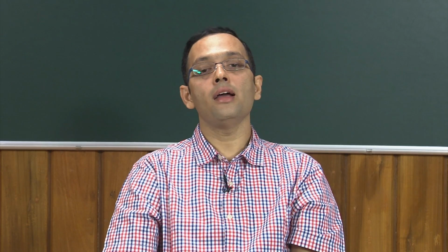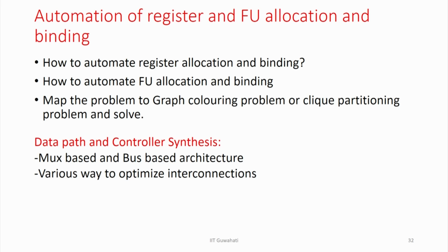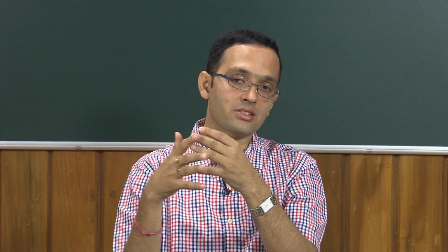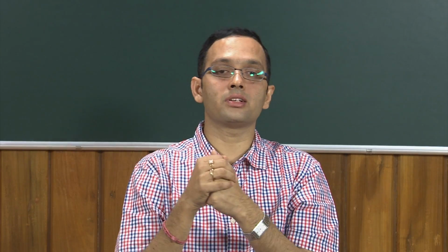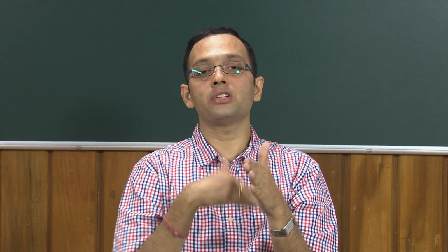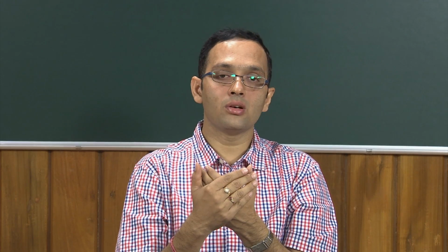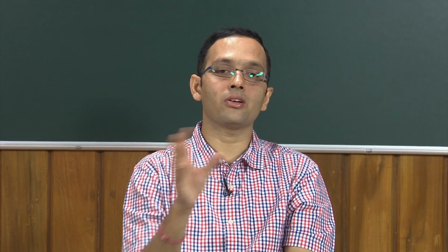My point here is to emphasize that the choice is not unique, you can have multiple choices and you never know, and all are interdependent. If you do one kind of scheduling, the kind of register sharing you are going to generate is different, or if you do a kind of register sharing or function unit sharing, the kind of interconnection that you generate will be different. We are going to talk about those techniques and how these things are interrelated in more detail in tomorrow's class. In tomorrow's class we are going to discuss more on various scheduling techniques, how we can automate this FU allocation and binding techniques, steps, and how the data path depends on all these steps. We are going to discuss that in the next class in more detail. Thank you.